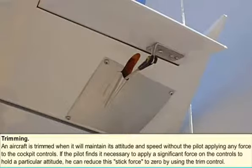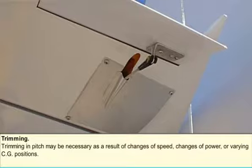An aircraft is trimmed when it will maintain its attitude and speed without the pilot having to apply any force to the cockpit controls. If it's necessary for a control surface to be deflected to maintain balance of the aircraft, the pilot will need to apply a force to the cockpit control to hold the surface in its deflected position. This force may be reduced to zero by operation of the trim controls. The aircraft may need to be trimmed in pitch as a result of changes of speed, changes of power, or varying centre of gravity positions.